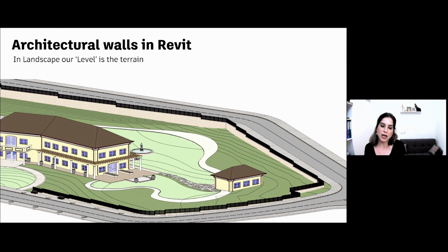So what I did over here, I selected the walls. I click on Arrange Walls, and this window has opened. Again, I'm not going to go into each and every parameter. I'm just going to say it allows you to define the heights of the walls, the elevation steps between one part and another. And it also allows you to set certain length parameters. So you can really control many parameters of the wall. So let's say I'm okay with that. Let's change this one. The steps will be 50 centimeters and then click OK.